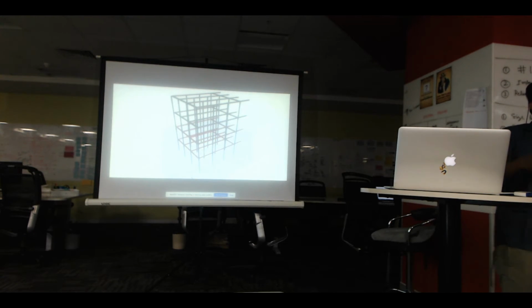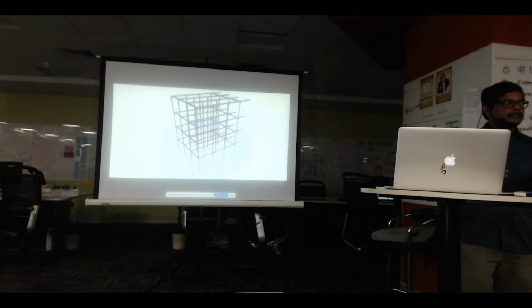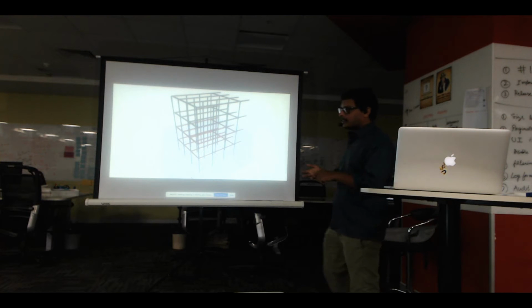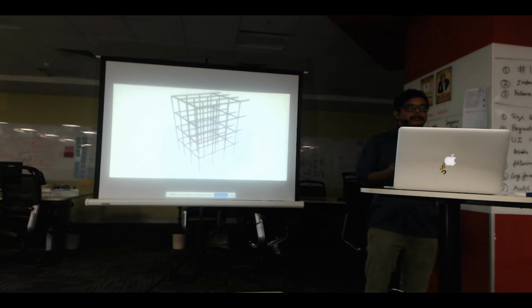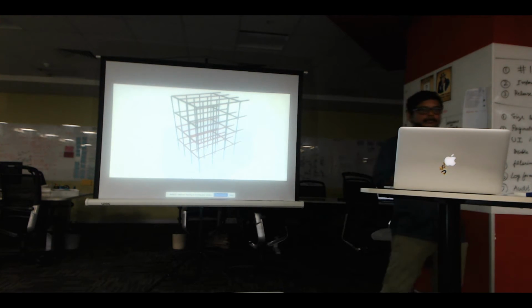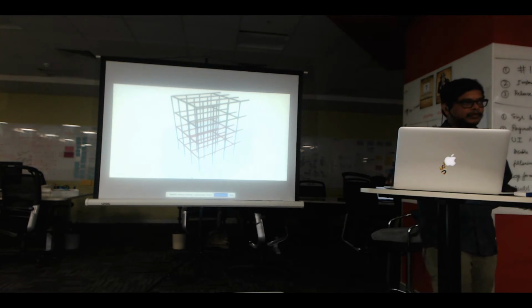So you kind of multiplex one signal to many. So again, with one single microcontroller, you could use many shift registers, and you could actually get 72 independent signal controls. So that's the solution for the first problem.